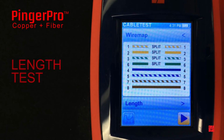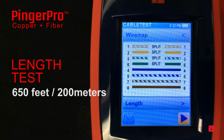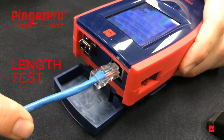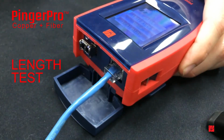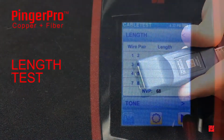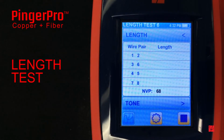A length test is used to electrically measure the length of a cable or identify an open or short fault and give the distance to the fault. This test is run from just one end of the cable and can be run from either end. The PingerPro will measure cable lengths up to 650 feet or about 200 meters. From the wire map screen, press the length button to go to the length test screen. Attach an Ethernet cable to the PingerPro. Make sure that the far end of the cable under test is not connected to the terminator or any device. Press the play button to run the test.